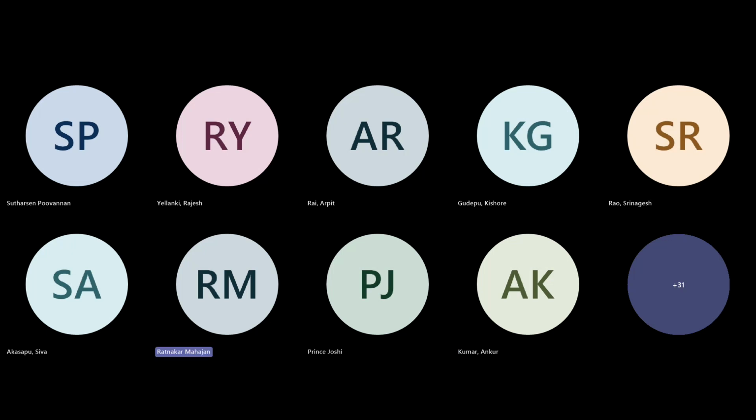Typically, when you have marine clays, as I showed in the case study of Agartala where we had very soft soil, a combination of prefabricated vertical drains or sand drains or columns, along with the geosynthetics, can be useful for ground improvement. So this technology is very much useful for port connectivity, where we are going to encounter soft soils, and it is one of the most cost effective compared to other conventional solutions.